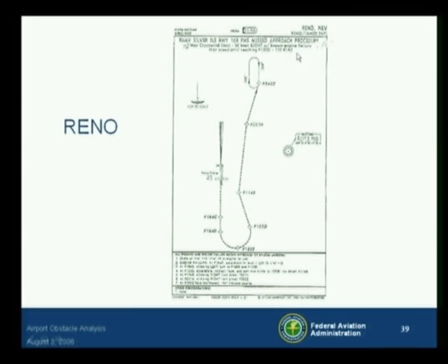These are the kinds of things we can do in this arena to get these things under control. The most beautiful thing about this approach is the pilot gets to the missed approach point, he flips a switch on the dashboard from VOR ILS to LNAV and lets the autopilot do its thing as it flies him out of there.